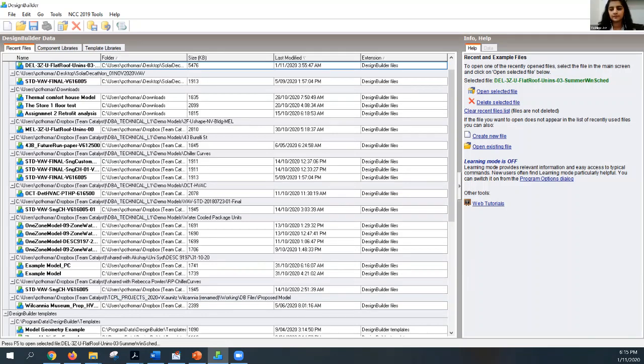Yes. I will do one thing. I have a colleague, as I said, who is much better at CAD than I am. I'll ask her, but I'm fairly sure that with SketchUp, the only way is to export to GBXML and then import that into DesignBuilder. Try and keep the model as light as possible. Make sure that all spaces are enclosed spaces, so you have 6 surfaces, because otherwise you lose something in translation. It's always hard to do those sorts of translations.